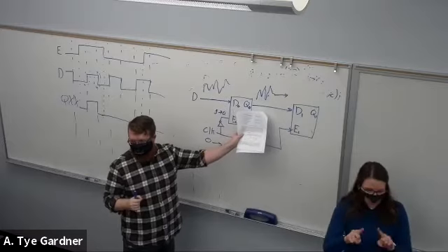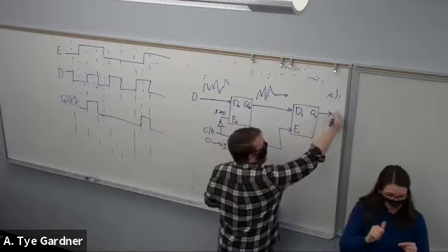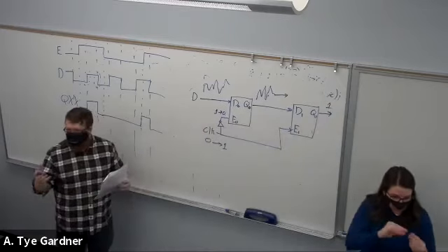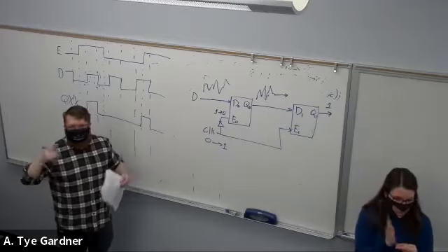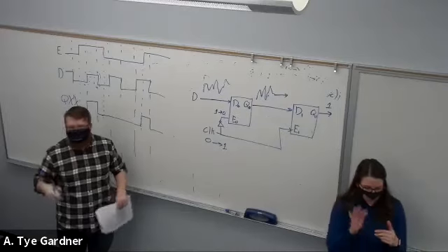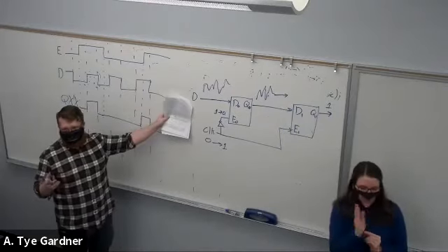It's locked in. There's no wiggles. So it's going to lock onto that 1 or 0. So when we rise from 0 to 1, at that exact moment, minus whatever the delay through the circuits are, it locks in and holds on to that and remembers it, regardless of what D's kind of doing over here.